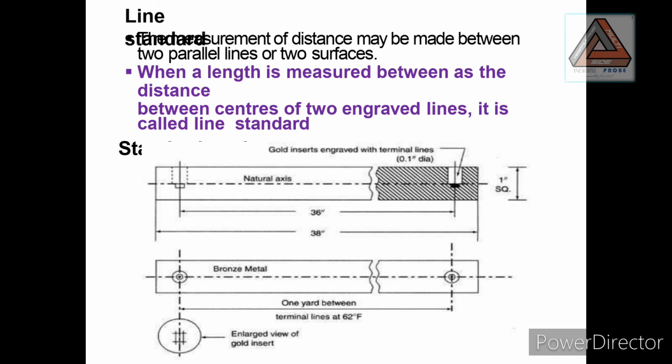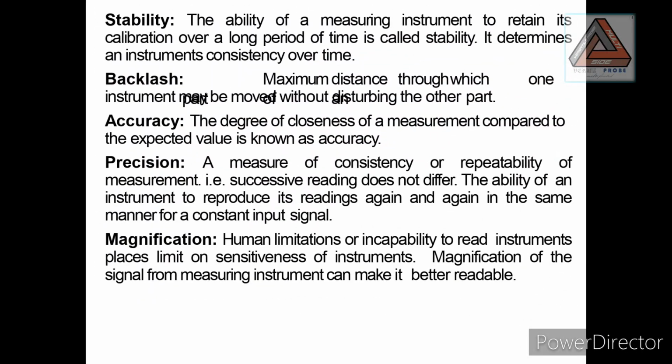Factors affecting the characteristics of an instrument: scale error, repeatability and reliability, readability, calibration error, effect of friction, zero drift, backlash, inadequate amplification, deformation when heavy workpieces are measured, constant geometry for both workpiece and standard. Factors affecting the person: training, skills, ability to select the measuring instrument and standard, attitude towards accuracy, planning measurement techniques for minimum cost consistent with precision requirement.